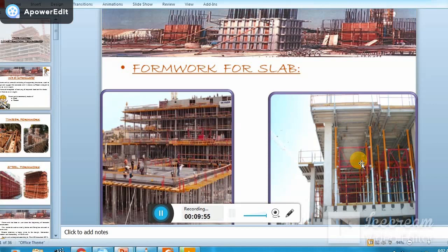How does it affect the design of composite section? The main purpose or the advantage of such shored concrete is that it initially provides lateral support, or you can say it protects the beams, that is girders, from lateral torsional buckling. So that is one advantage. The other advantage is that the beam has nothing to support.